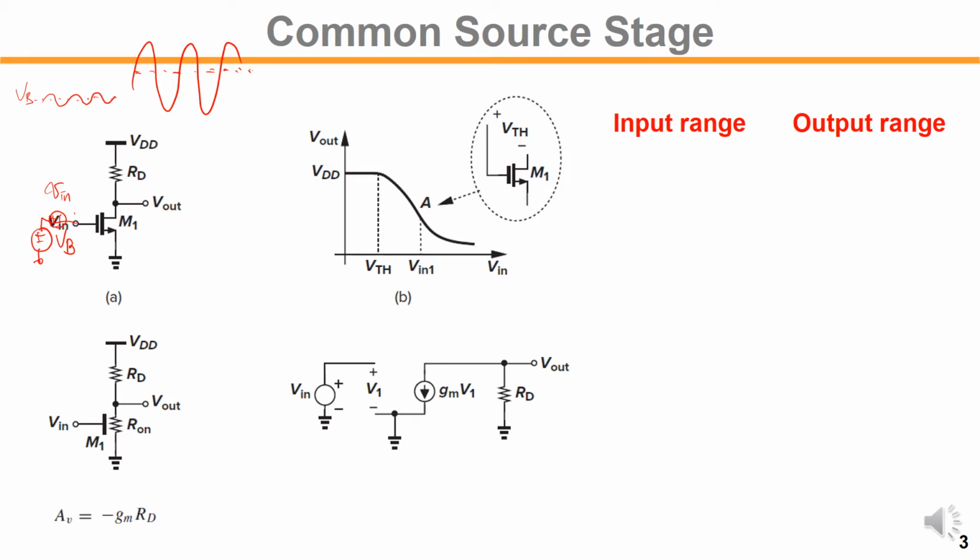So we have to determine the proper level of the current through this device, let's say IDS. To determine the proper level of the current, we first have to identify the required range of this amplifier at the output. At the output, how far up can the device go? The maximum voltage at the output range is VDD. The lowest level would be where?